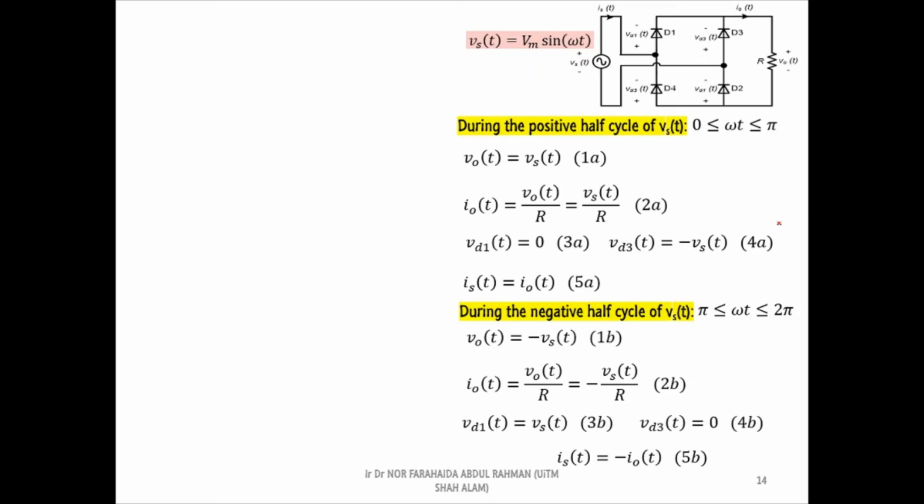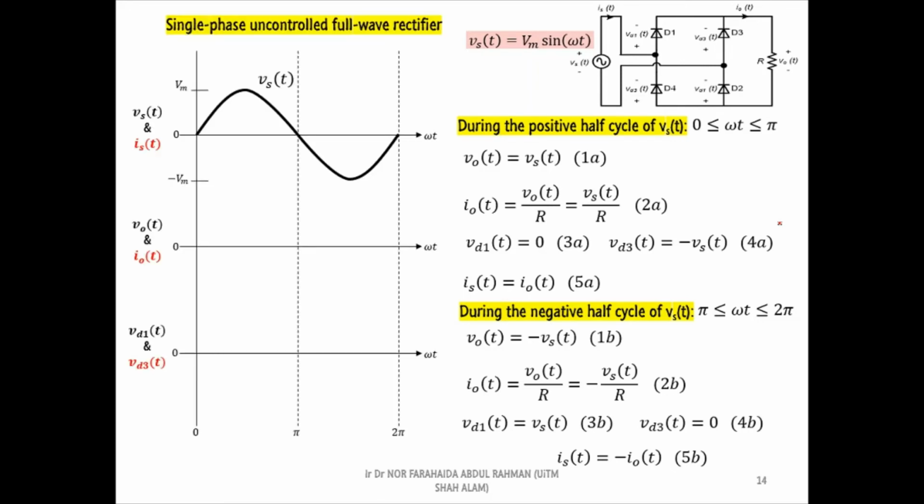When you want to start the drawing, first sketch the axis and the supply voltage waveform. Then, label the conduction range of all diodes. Please remember that the conduction range is referring to the omega T value in which the diode is conducting current. Based on the labels, we can see that each pair of diodes has a different conduction range.